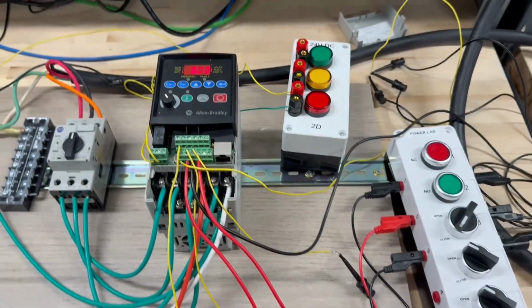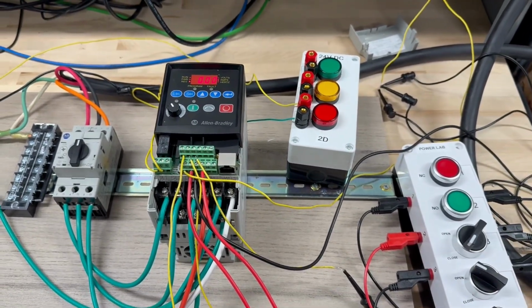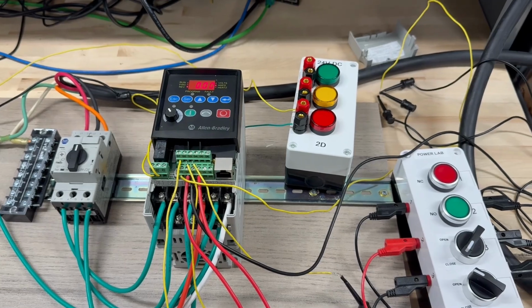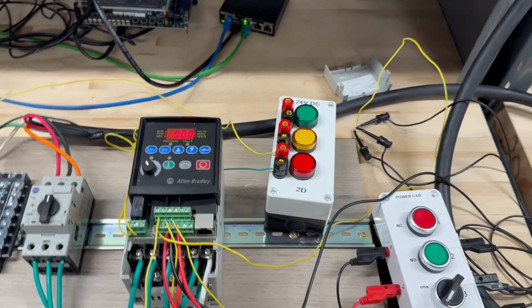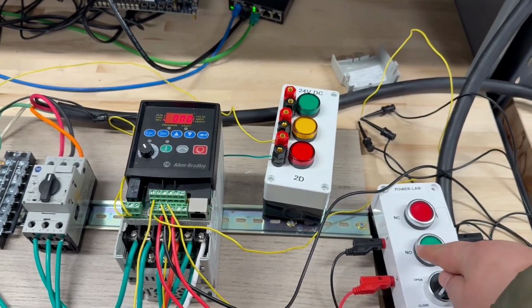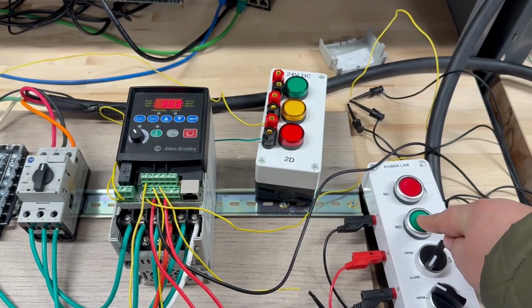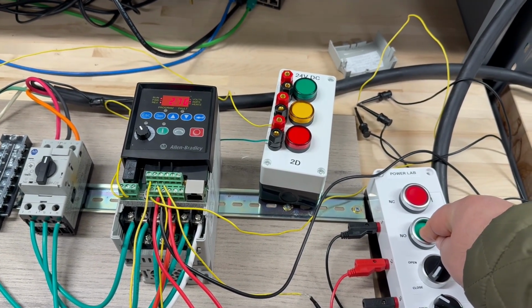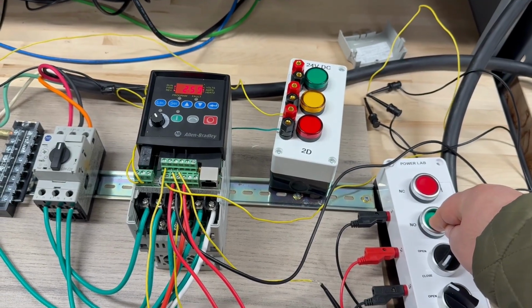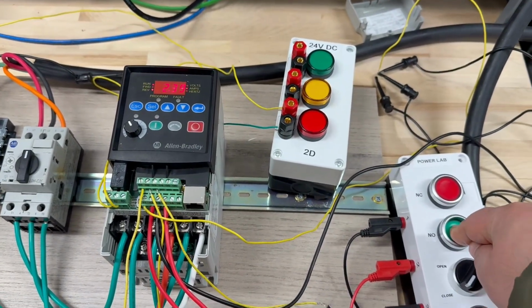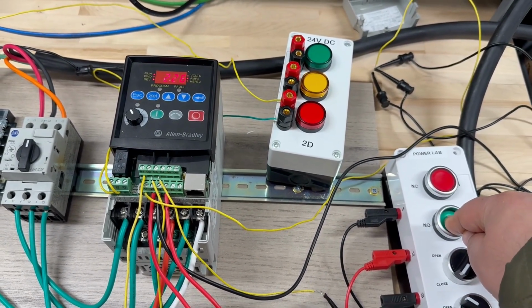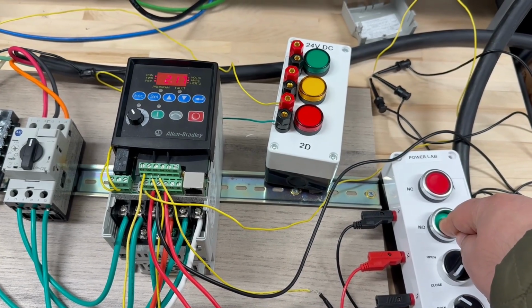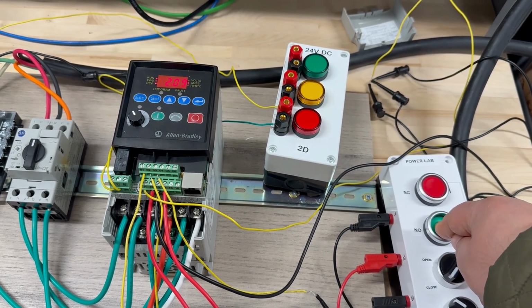Let's start it. I hold my start, and each time the error happens, you can see exactly how it retries 2 times with a 5 second delay between them. So I push and keep the start, and it's starting. Usually there is a delay. Right now it's 2.3 or 2, over 1, but it takes time before you see that fault.